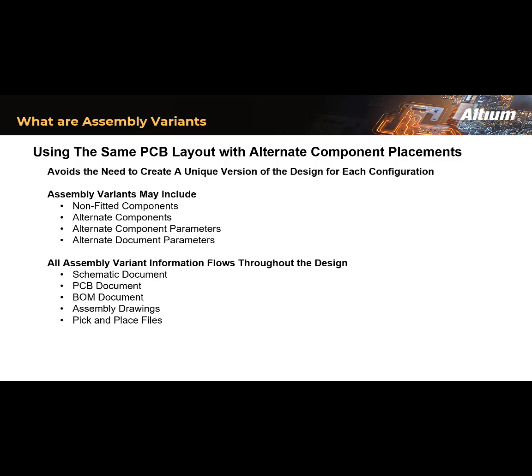In practice, a design variant uses the same base PCB fab, but the PCB is loaded with a different set of components specified by the variation. Then that particular variation can be nominated when you're generating your manufacturing outputs for your bill of materials, pick and place, assembly drawings, etc., which in turn will determine how the product is assembled.